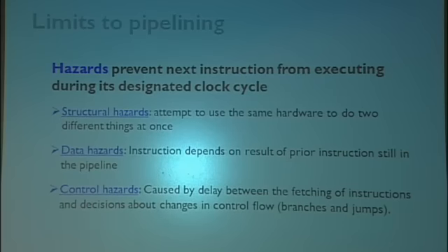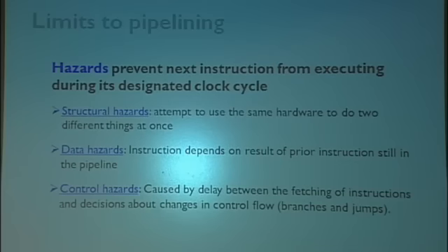And there are things called data hazards. That means you're trying to run these things one over another, but logically, they have to run serially. So there's a data dependence, which I'll get into, that makes it impossible to run these things in a pipelined fashion. And finally, there's control hazards: things like branches come and interfere with that.